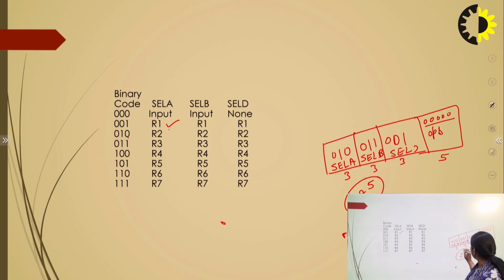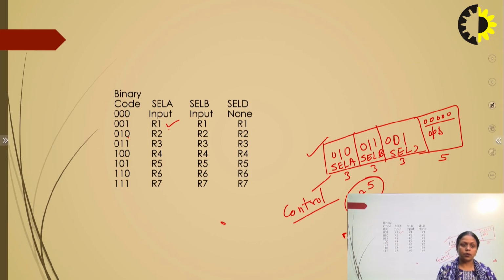Why do we keep 5 bits for the operation? Because our ALU will have 2 raised to the power 5 operations, and only one operation will be performed by this instruction. So, with the help of this table we can design the control word. This is known as a control word, and it is designed by the control unit. The sole responsibility for generating the control word belongs to the control unit. So, the control unit is a major part of our processor organization.